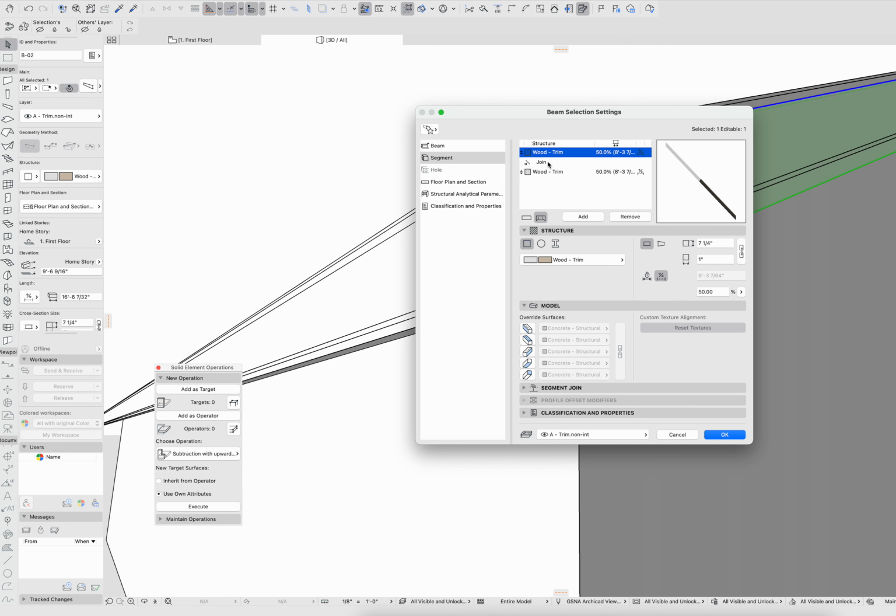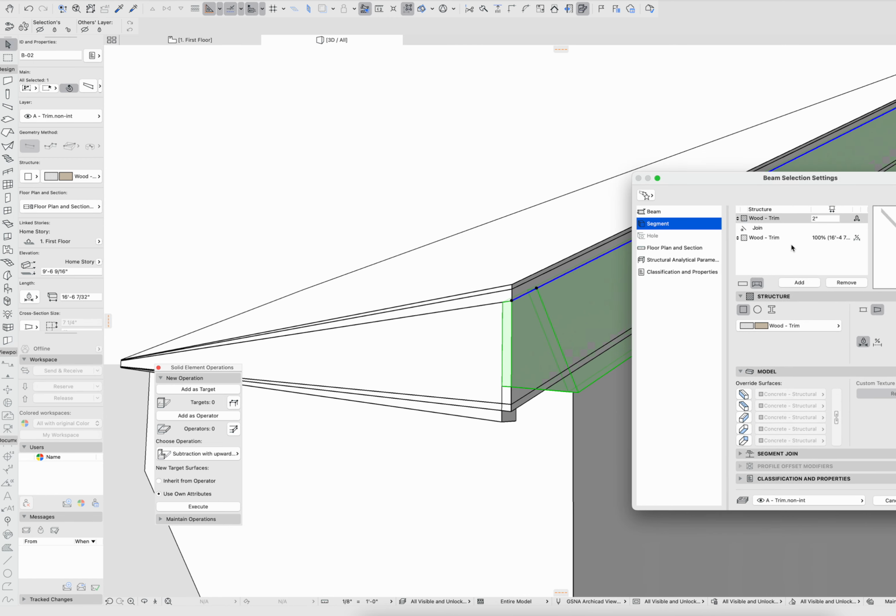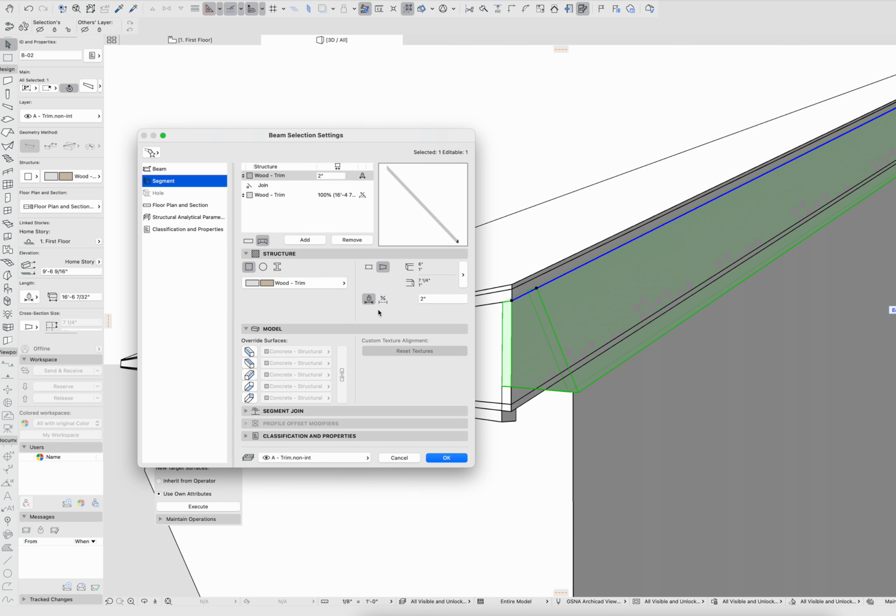This is the top segment, this is the bottom segment, it just depends on which direction you drew the beam in from. In this case, we'll say that this is fixed, and maybe its length is 2 inches, and that has a taper to it. So if we say that that taper starts at, let's say, 6 inches, and we'll just see where that gets us. So you can see right there, you're starting to understand what that actual height and length would be. Obviously, you could do this in elevation and get the actual dimensions of those things. Here I'm being just kind of loose for the sake of the model.